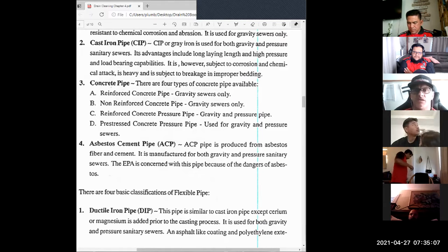Asbestos is actually very easy to deal with when airborne. It's when you're in a confined space and you're breathing it over a long period of time that it's a problem. I'm not saying it's good to breathe a little, I'm not saying that at all. I'm just saying it's not a hard thing to deal with. When cutting with water and with a respirator, and then properly dusting off and washing off prior to removing the respirator, you're actually safe dealing with it.